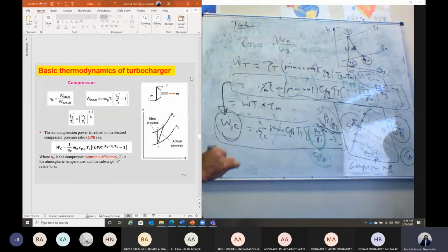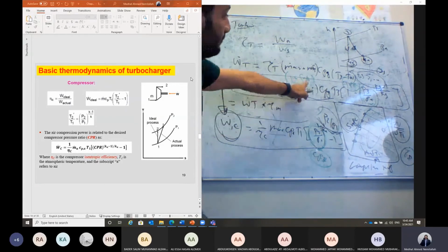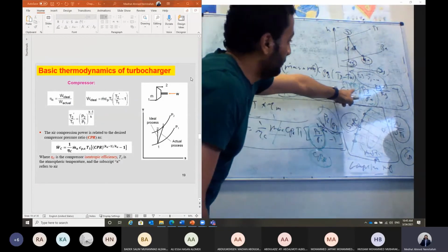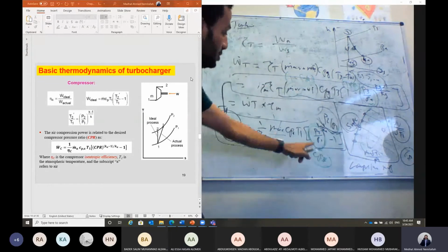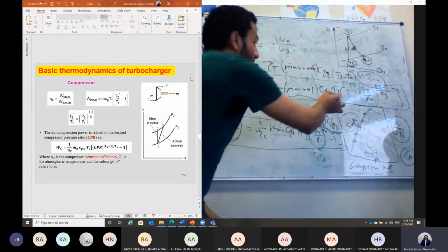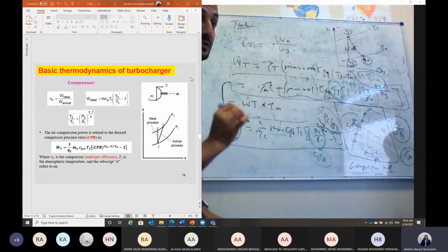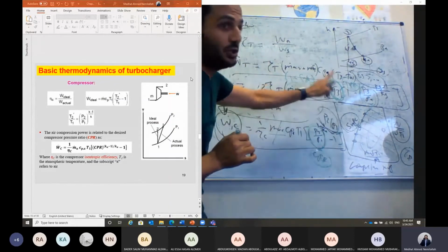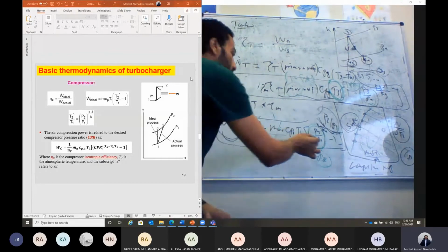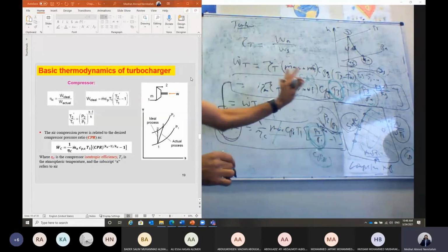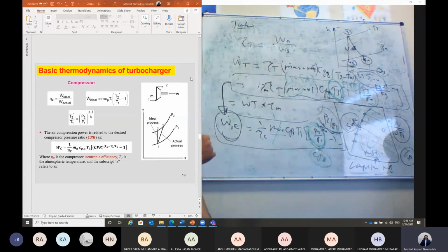So now, Shabab, we have resulted in a matching equation that is a function of fuel to air ratio, turbine pressure ratio, compressor pressure ratio, and the temperature T3, at which the exhaust valve opens. This temperature in this case will be T3. So we don't know all of these values. We have 4 unknowns in this equation.